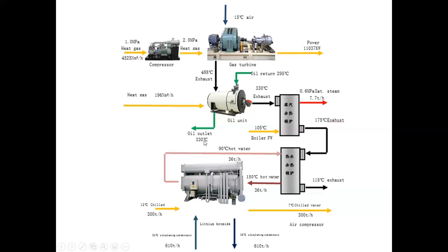And we asked him why, and he says because they had pitting, corrosion, oxygen pitting. Well, probably they had oxygen pitting because he wasn't venting any air from his deaerator because he didn't really understand. And so it was causing him all kinds of corrosion issues. But then we went inside and he had a bunch of VFDs on his boiler feed pump and his combustion air fan, which is stuff we tell people to do all the time over here that half the time they don't do. And so on one hand, he was really, really good. On the other hand, we got some improvement we can do over here.